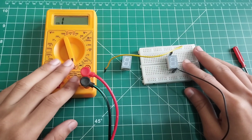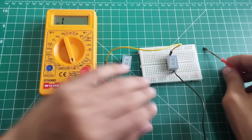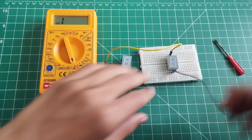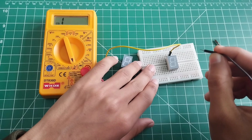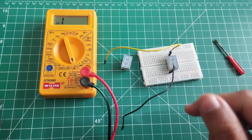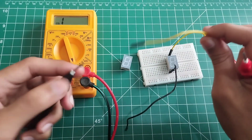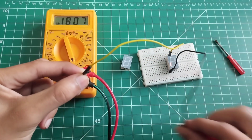Now what I'm going to do is test each of the 7 segments individually, whether they are working fine or not. And I have set the mode of the multimeter to the diode testing mode, because an LED is also a diode. So I will remove the jumper wire from the middle pin and insert this jumper wire at any of the terminals, like the leftmost terminal. And I will touch the probes of the multimeter to these black and yellow wires. The yellow wire is connected to the middle pin, which is the ground, so this will be connected to the black probe, and this black wire will be connected to the red probe.